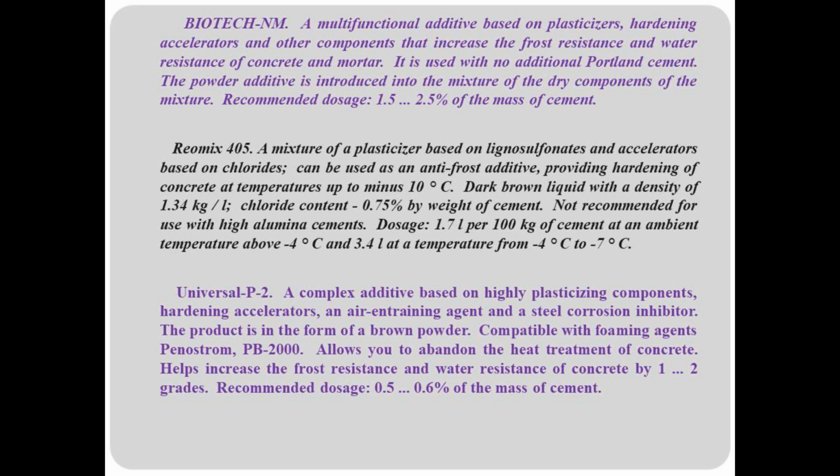Rheomix 405. A mixture of a plasticizer based on lignosulfonates and accelerators based on chlorides can be used as an anti-frost additive, providing hardening of concrete at temperatures up to -10. Dark brown liquid with a density of 1.34 kg/L.